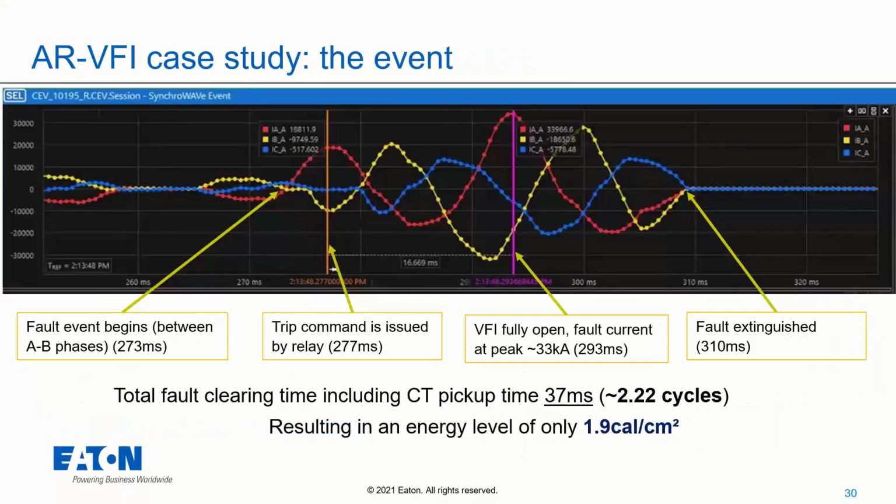So I actually do have those waveforms for that event. If we look a little bit further, the energization starts right around the node where all three phases are no longer synced up at 0. That's between the 260 millisecond, 270 millisecond marks. And then we start to see typical A, B, and C voltage waveforms. Right at about 273 milliseconds, you start to get some crossover and anomalies where the A and B phase start to spike, which is where we start to see that overcurrent event arcing through that fallen shipping support. It ended up reaching a magnitude of about 33 kA.